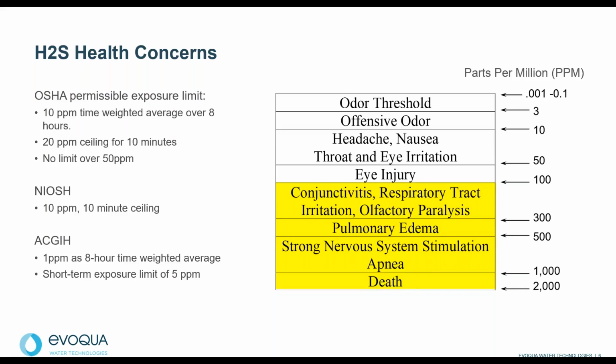So why are we concerned about treating this gas specifically? It's because hydrogen sulfide gas is toxic to human beings. Typical ambient air and atmospheric conditions for municipal services job sites fall into the quote-unquote offensive odor concentration range for hydrogen sulfide, but nonetheless, higher unsafe concentrations of hydrogen sulfide are sometimes discovered.